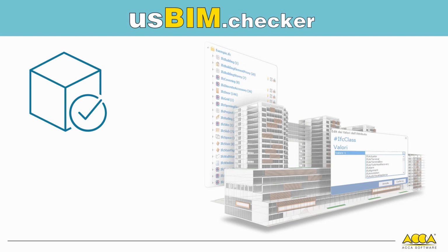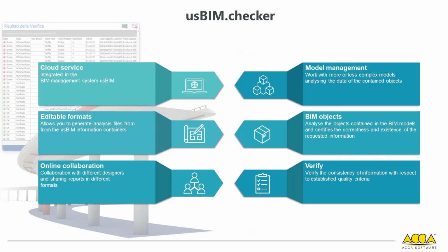In summary, usBIM.checker allows you to verify the existence of object properties, view and control property values, verify the accuracy of the values, generate and export property control templates, create a congruence report between properties and values in the IFC file. Now, let's delve into the application's characteristics.